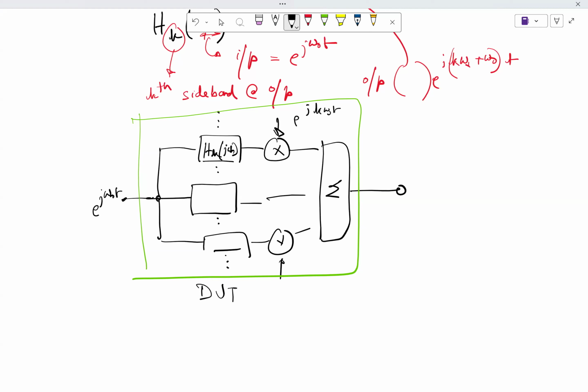You are putting a spectrum analyzer. You are going to see something, right? What are you going to see? Why multiple frequency? LTI system. Yeah. An impulse at the same frequency at which you have given the input, correct? And anywhere else, you are not going to see anything other than, you probably will see noise, but experimentally, you will never get rid of noise. You're going to see noise, but you are going to see an impulse at the input.